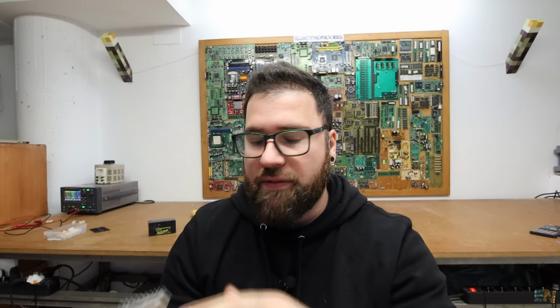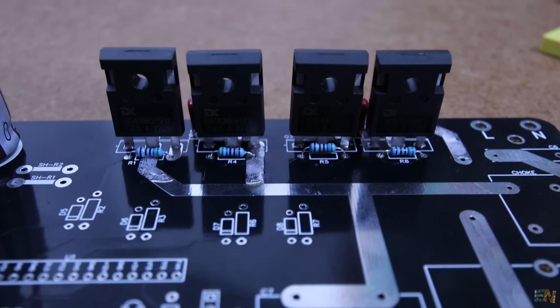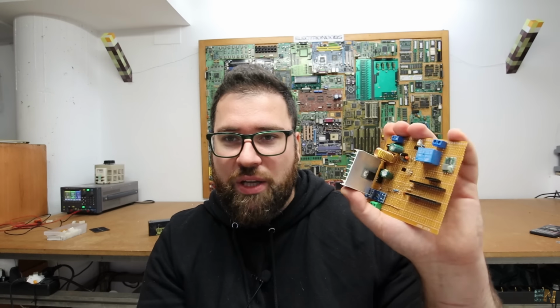And other changes that this MPPT will have are some big changes for more power. For example, instead of this small MOSFET, which could work up to 55 volts, I want to use some IGBTs, which could handle a lot more power. I think these IGBTs can handle up to 600 watts, and if you have more than one, you can handle even more current than that. And also I want to make an MPPT that will work with up to 102 volts or something like that,